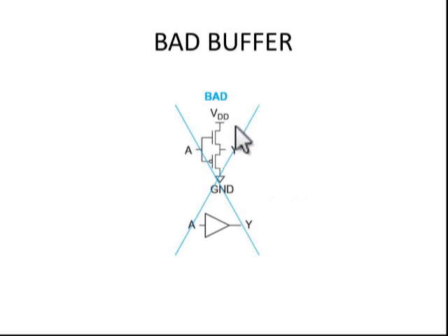So first we will take a simple example. Before we move to CMOS, we will try this one. So here the NMOS is connected to VDD and PMOS is connected to ground. Actually the NMOS has good 0 and bad 1 property. That means when this NMOS is on, and it is connected to VDD, now output goes to 1. So it's a degraded one because of the property of the NMOS.